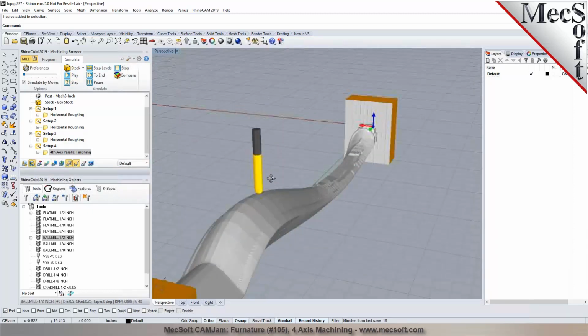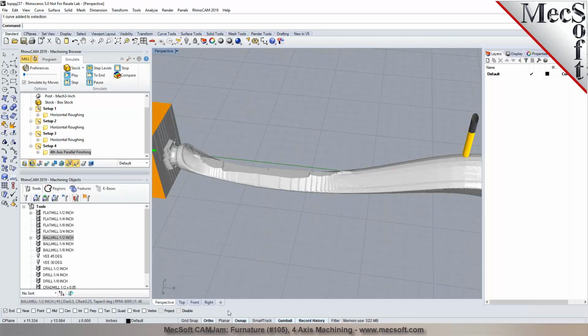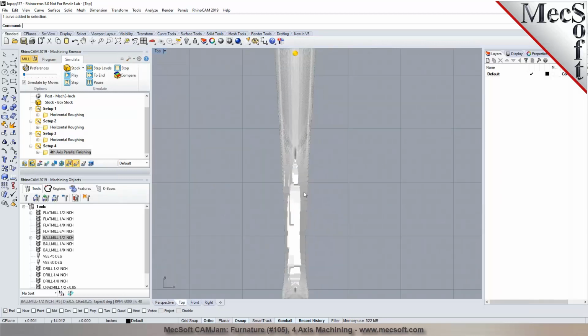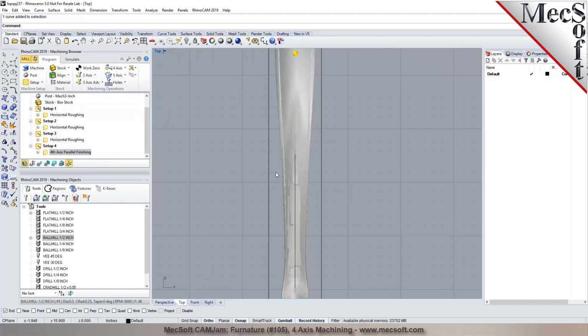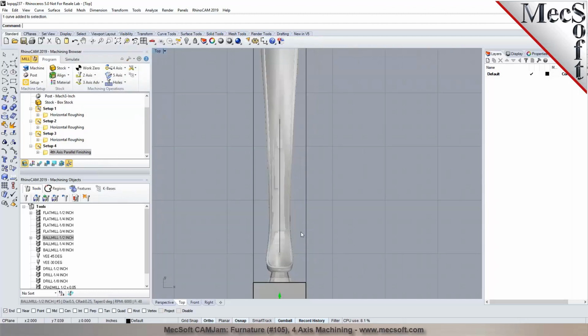So we programmed most of the areas except this particular section in here where we could not dip the tool below the rotational axis, right, on these areas. So one of the ways you can program this would be a boundary selection. For example, I'm going to turn off the ortho snap right here and pick a boundary around the part. Just create a very simple boundary as you're seeing it in Rhino. Nothing fancy, just using this boundary as an area to contain the toolpath.